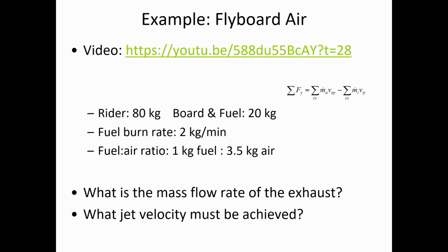So we have to have 981 newtons of force to hold the 100 kilograms level if gravity is 9.81, and the mass flow rate was only 0.15 kilograms per second of the exhaust. So that would mean that you'd need to have a velocity of 6540 meters per second. That's really, really high.